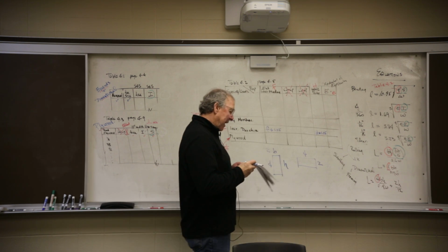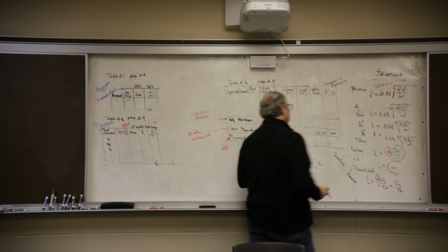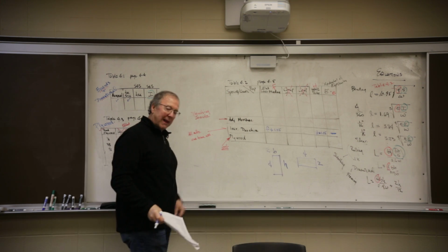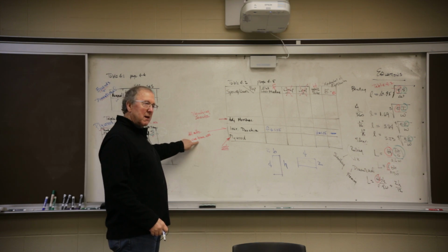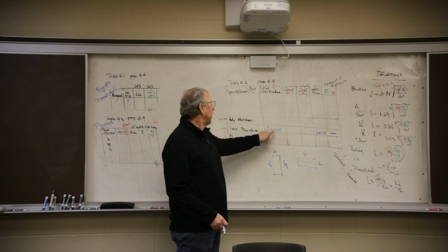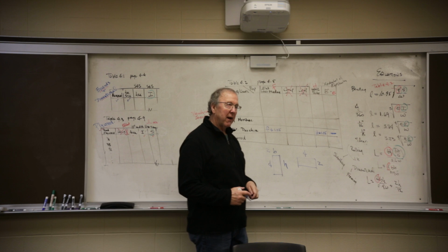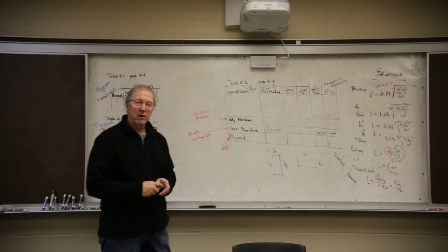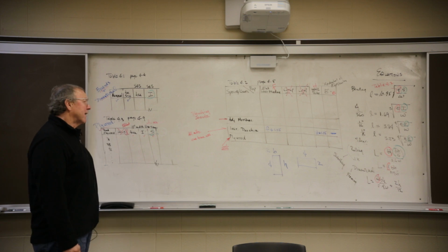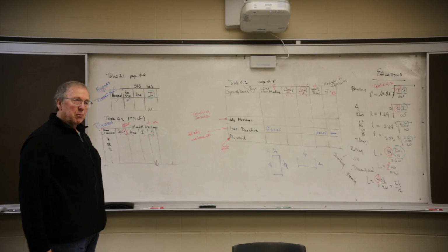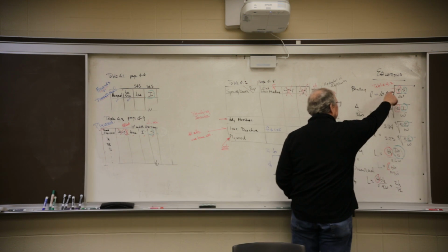And then it says do nothing for modulus. So when you look up your allowable stresses, if you're going to use it one time only, you're going to take those numbers and multiply this one by 1.25 and that one by 1.25. That increases it by 25%. So that gets us in a position where we've got data put together that we can fill all these blanks, except for W.